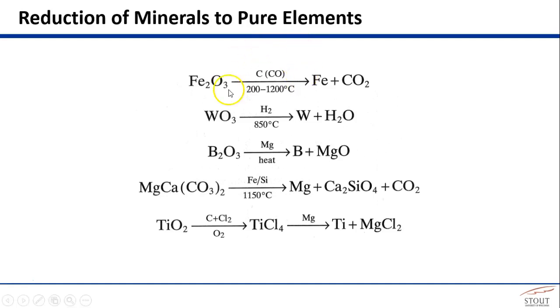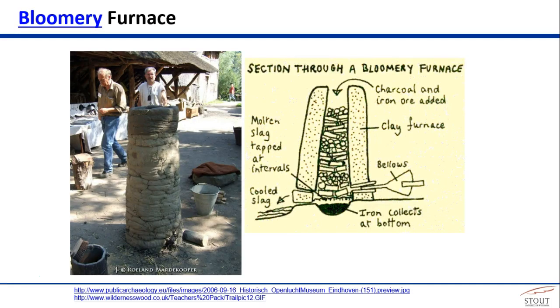And so when done properly, at the end, you would have molten iron at the bottom, often a layer of melted slag on top of that iron, so you tap it down below the slag level, and then you're going to blow off carbon dioxide off the process as a byproduct of the coal that then stole the oxygen from the metal. Genius. Now this is done in a highly automated way these days, but it can be done in a very low-tech way. The bloomery furnace.